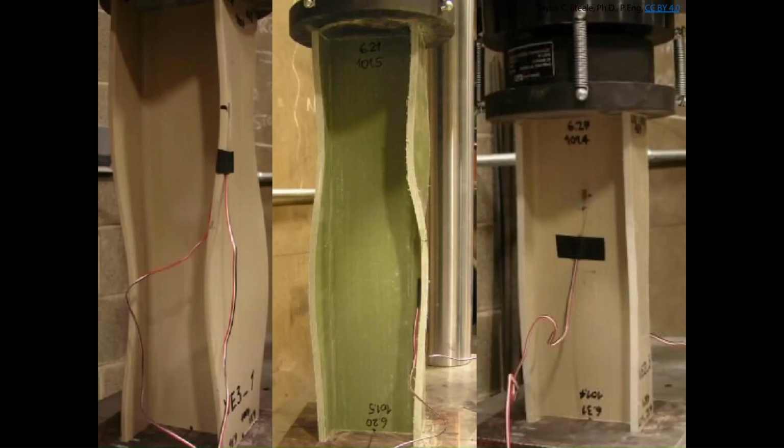So that actuator is pushing down on the section, and before they got yielding of the cross section, basically before they reached the load AFy, we got buckling of the flange, and that reduced the load that could be applied to the cross section.